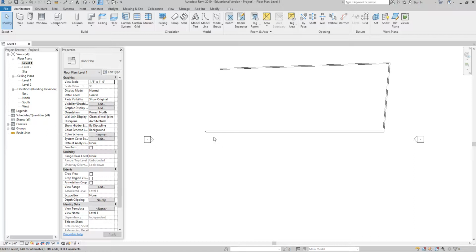So the way the wall command works is that I click to initiate in the drawing space. I move my cursor in the direction I want it to go. I click again. It's as simple as that. That is the line tool. Okay. The way that we just drew that wall wasn't really what I'll call dimensional, meaning we didn't input a dimension to make it. We just clicked. We kind of free-handed it, right?